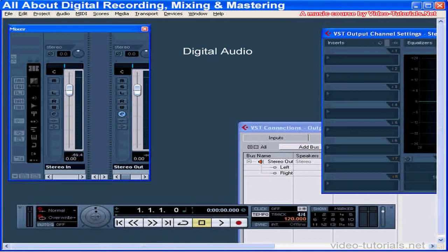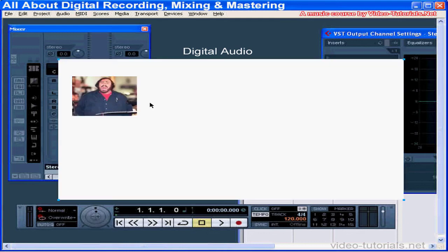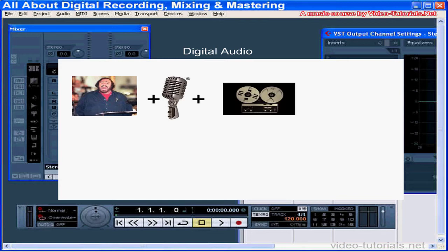We'll begin with a recap of the energy and electronics involved. First, you need a sound, something that disturbs the air and generates sound waves. Next, you need a transducer to convert this acoustical energy into an electrical signal, a microphone, for example. Lastly, somehow you need to store these voltage variations produced by the transducer so that you can reproduce them afterward.